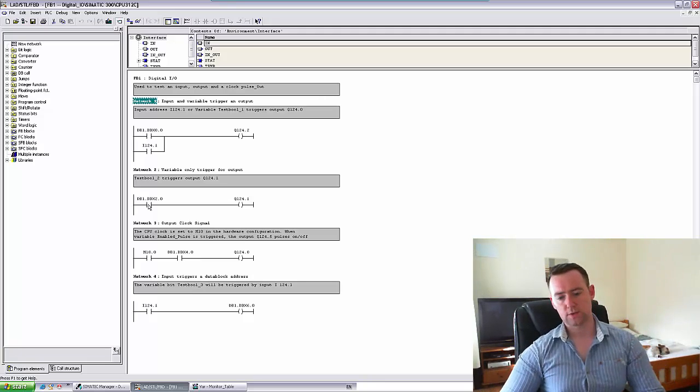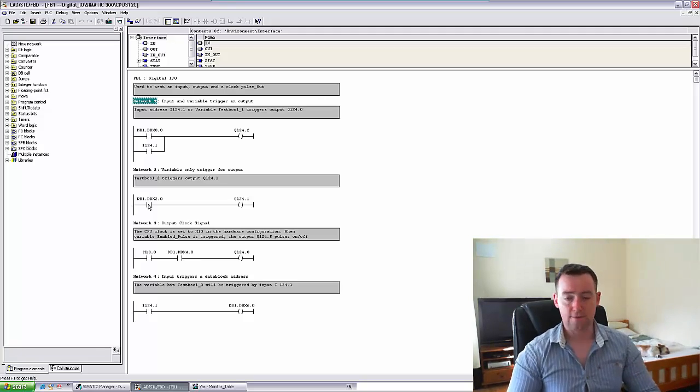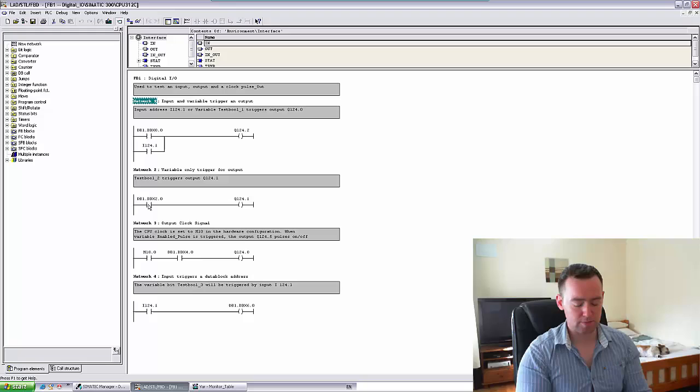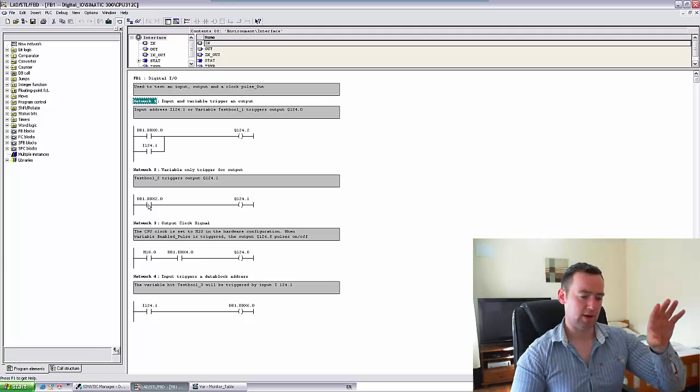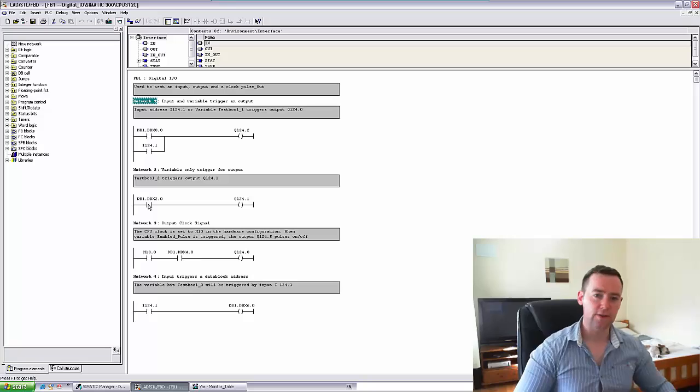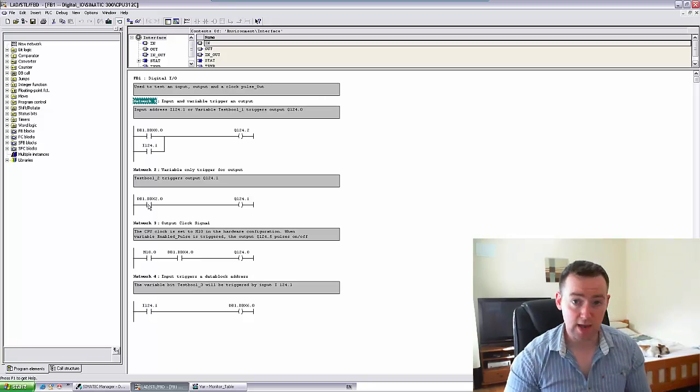So what I'm going to do is have the S7 side here, as I said, and then create forms in iFix where I have an indicator and a button, right? That's a really simple way to show I have my program in the PLC, my input and my output, and then my tag database with the S7A driver, and then I'm on the iFix side, and I have my database there again, right?